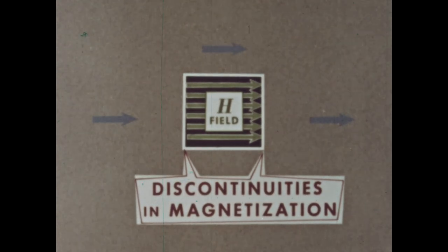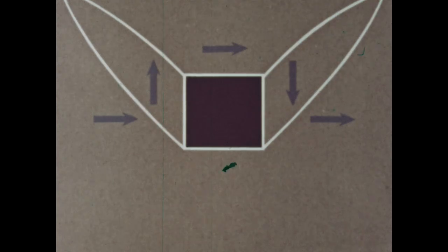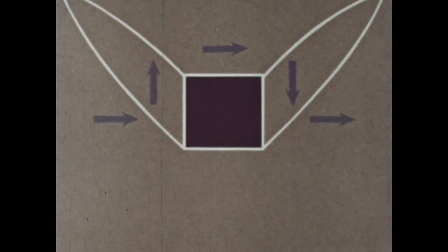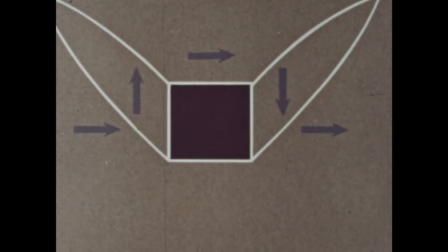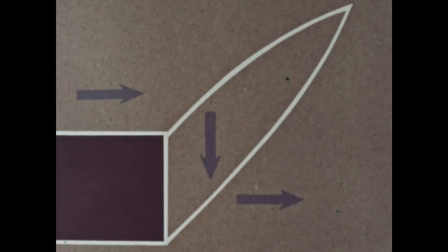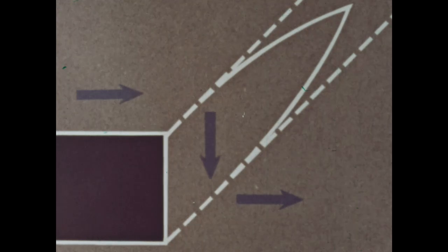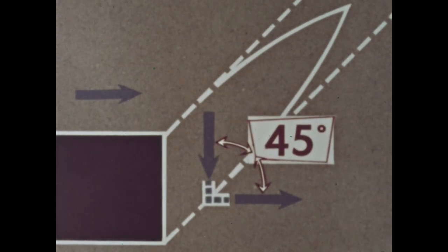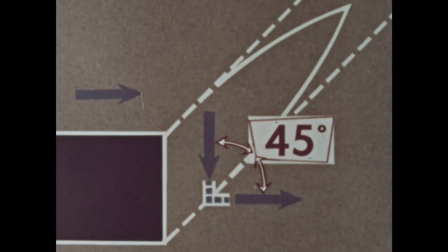In many cases, however, this energy is reduced by the formation of spike-shaped domains. In iron, the magnetizations within the spikes are at right angles to the surrounding magnetization, and the discontinuity at the surfaces of the inclusion is drastically reduced. The walls that form a spike domain tend toward the 45-degree angle that would bisect the right angle made by the magnetization vectors.